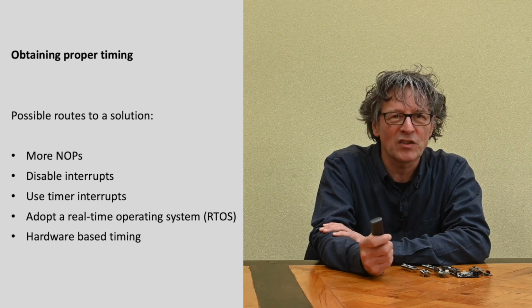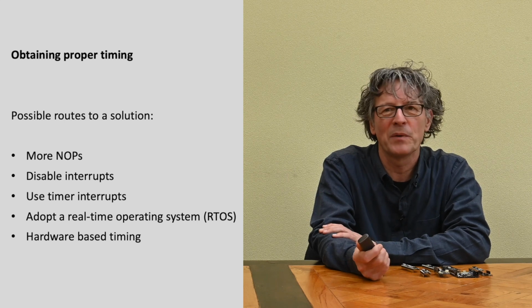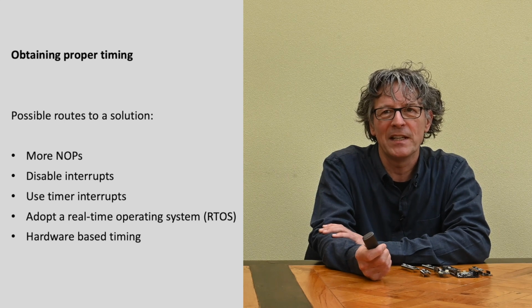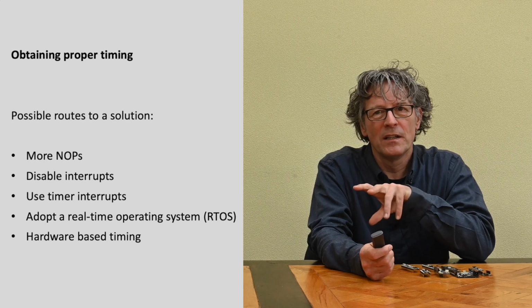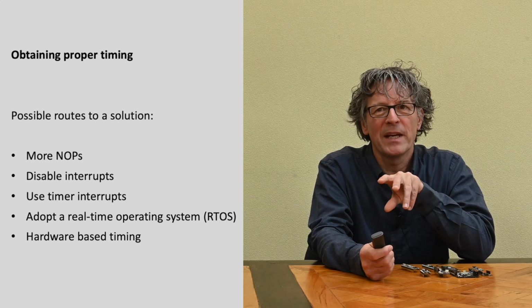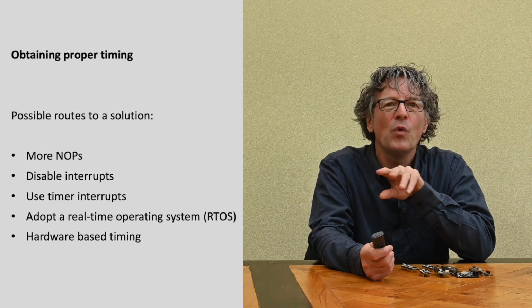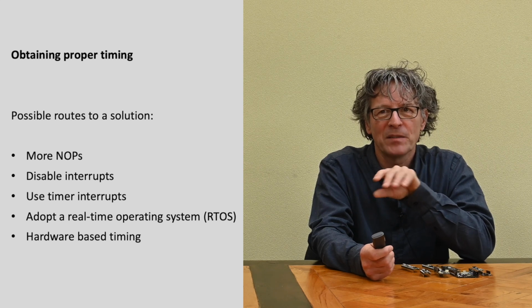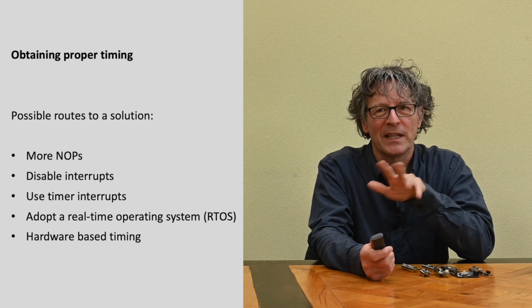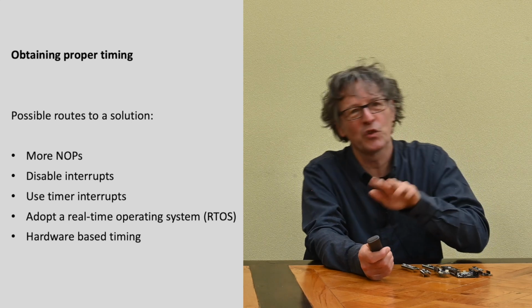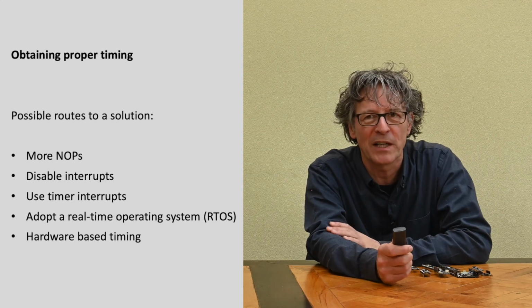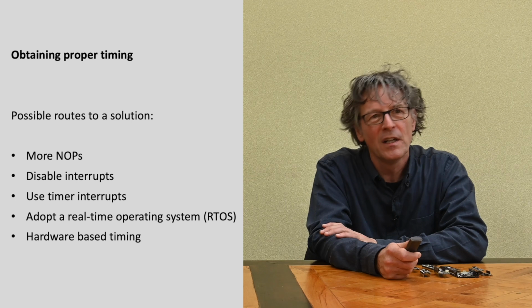However, it does come with its own considerations, and one of them is that you really have to make sure that this hardware interrupt, this counter interrupt, only comes at the moment that you're really sure all the other code is ready. So kind of the worst case things in the user interface and whatever, etc. Otherwise you would have unreliable code.